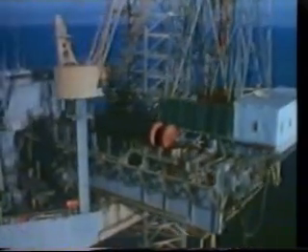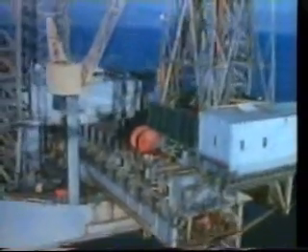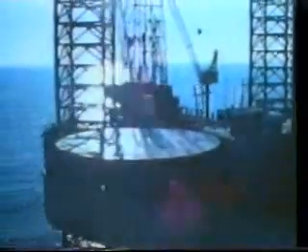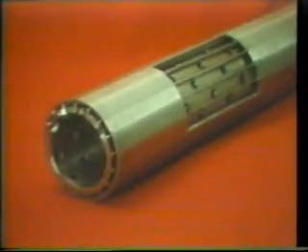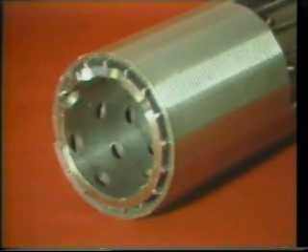In some places, such as the U.S. Gulf Coast, stimulation is not needed to induce production. In fact, the formations are already so unconsolidated that they themselves actually flow into the wellbore, creating an entirely different completion requirement, sand control. Methods for controlling sand production have generally involved one of two approaches: a metal or sand grain barrier which screens out the formation sand but does not inhibit fluid flow into the wellbore, or an epoxy resin which is injected into the rock and hardens to form a consolidating binder for the formation sand grains.